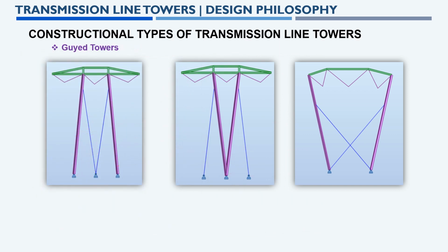And these are the guyed towers. Guyed towers occupy more space, because the right of way requires more space, since the guy will span more than 10 meters. It will occupy more than a 10 meter area surrounding each tower, but it depends upon the height of the tower. So these two structures, pillars, are used to support laterally by using guy wires.